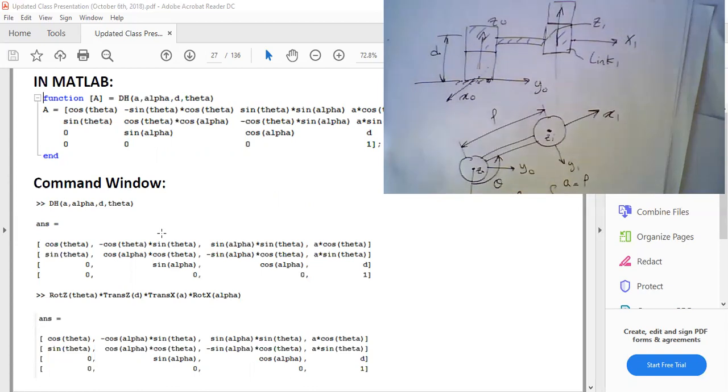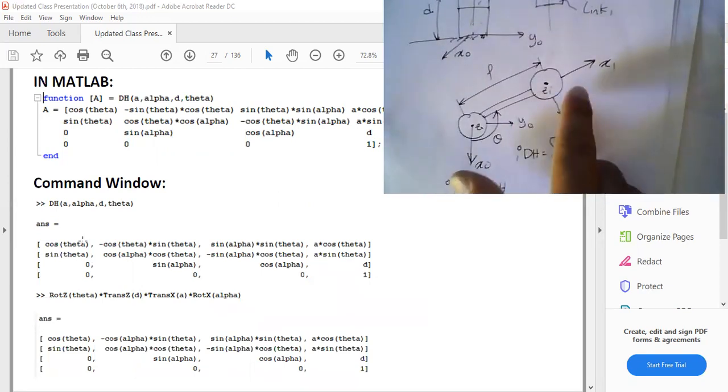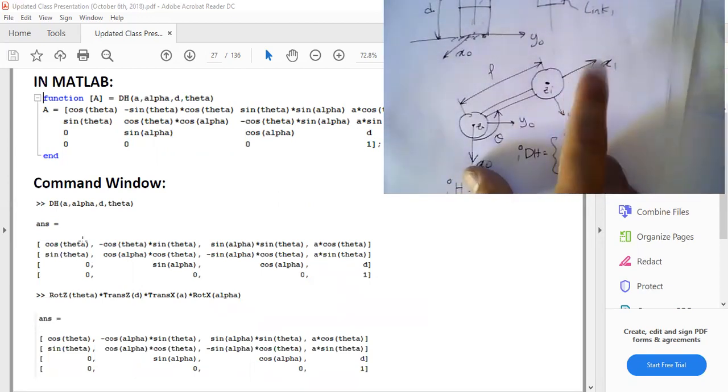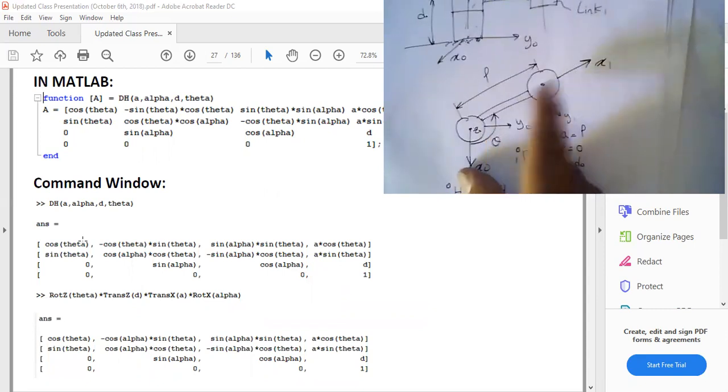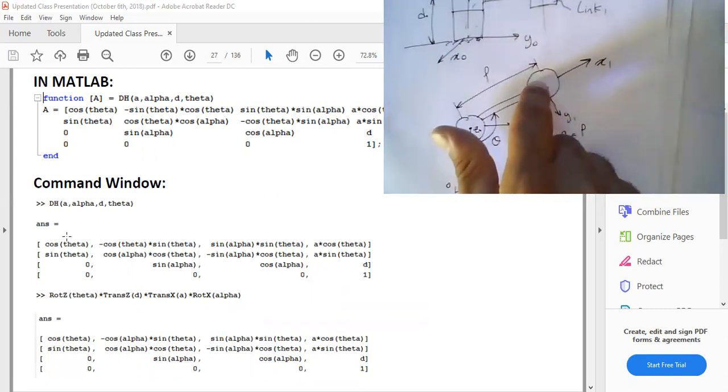So guys, you can now use these building blocks to build really modern robotic systems, and you can begin to comprehend how robotic manipulation essentially works. The basis of that is to really understand frames and how I can go from one frame into another. Later, we're going to use these to do the inverse kinematics. Essentially, we're going to find what theta should be in order for this guy to be at the desired position.